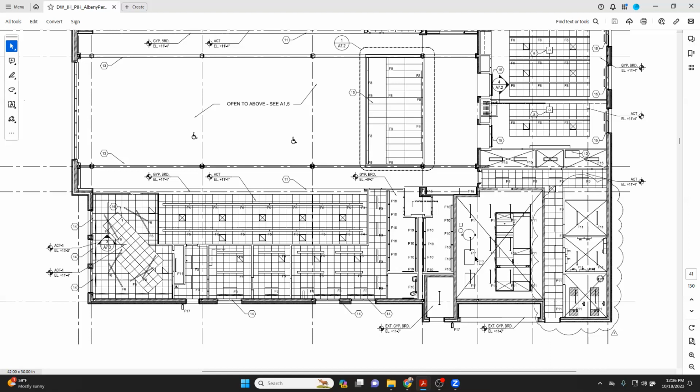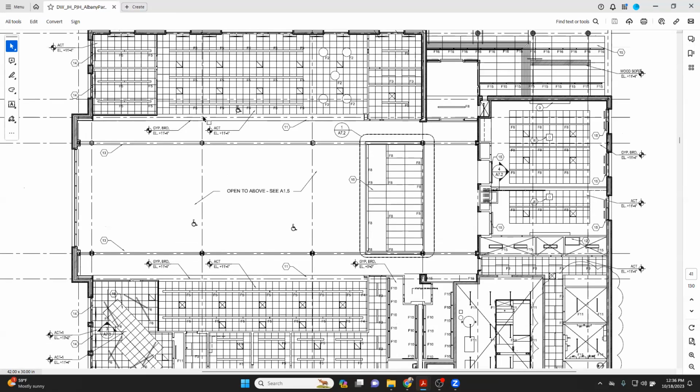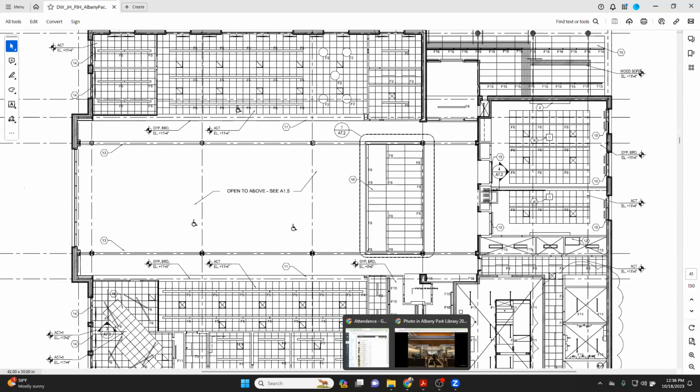And again, if you want to review what's required, just simply look at 8.4 and 8.5 to show you where the ceilings belong. There are also little level tags here that show you whether it's acoustical tile ceiling or ACT, and gypboard ceilings, and the heights of those. So these are both 11 to 4. So this ceiling here and that ceiling there are basically at the same height.